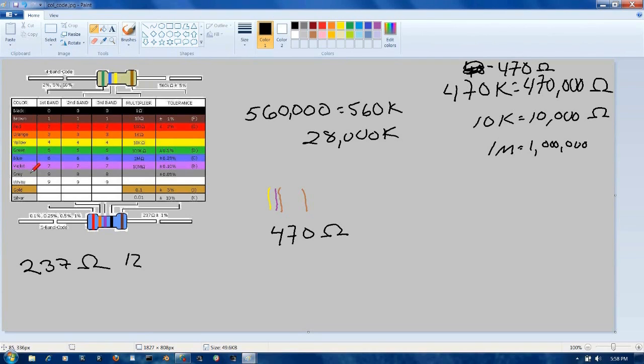So that's the rainbow. Outside the rainbow, you go from darker to lighter: black, brown, gray, white. So dark to light, and then the colors of the rainbow. Black is 0, brown is 1, red is 2, orange is 3, yellow is 4. Right now my fingers are going up as I'm counting. I'm using my fingers to count, and that's okay, to figure out what these values are.